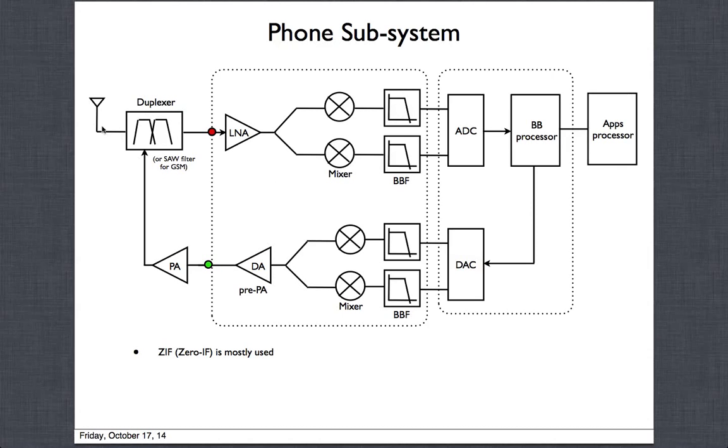And also the difference is, from the antenna, the SAW filter filters the receive path. The transmit path doesn't go into the SAW filter for GSM. This is only true for cases where we need the duplexer. The TX will also go through the duplexer. But in GSM type cases, GSM which is also 2G, which is also Edge is a standard, but I'm just calling that whole 2G thing GSM. Okay, there it will go straight through the antenna, maybe through some switches.